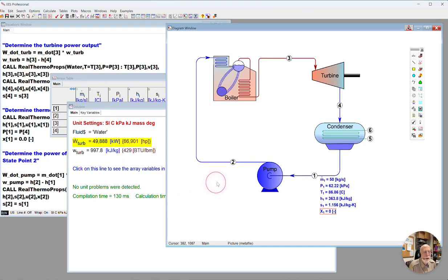And we're good. Sometimes when you calculate, when you have quality in the superheated or subcooled range, and you've asked for quality, it will give you an error signal or a warning window. Just ignore it. It's fine. If you look at your array, it will show up as minus 100 or plus 100. Just be aware. It's basically warning you that you're outside of your parameters where quality is a valid item.